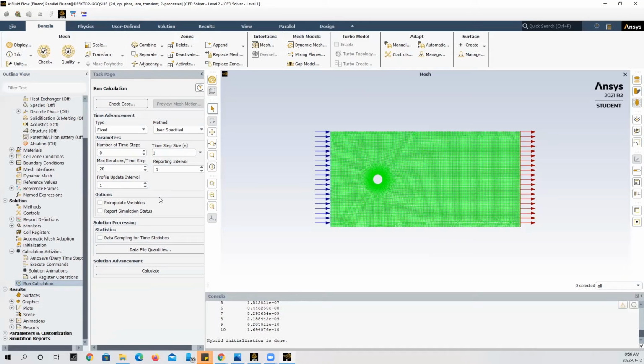Therefore, it would be good to specify the size of the time step to be at maximum 250 so that we can take a time step at least at the boundary of every smallest element, or make it less than 250 in order to take a time step in between the smallest elements. If we were to make it larger than 250, then we would be skipping elements in our mesh, and this may lead to an inaccurate result during the CFD calculations.